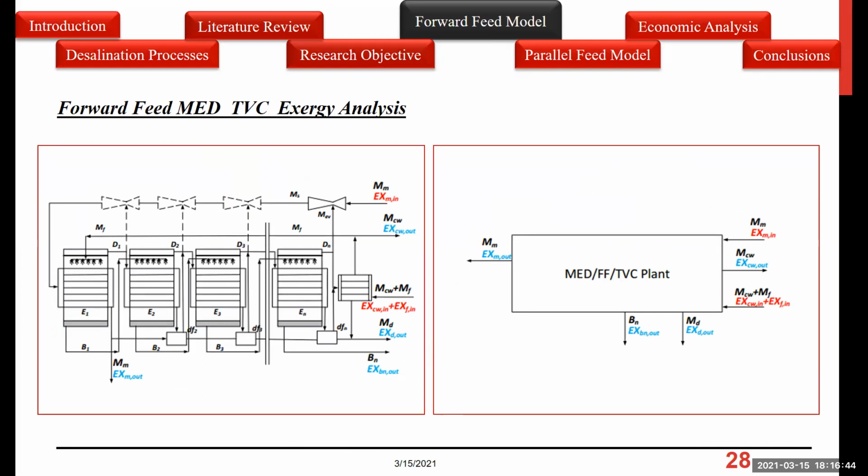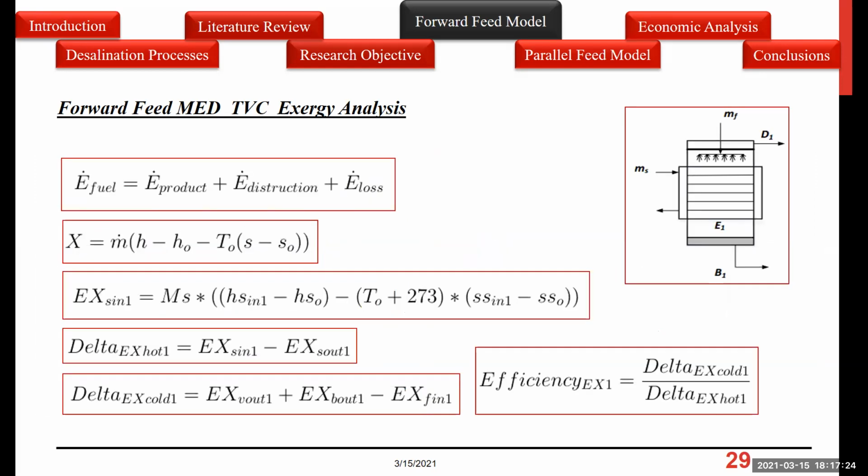Now, this is for the unit analysis. What if we need to do a second law analysis? For the second law analysis, we need to look at what are the entropies in and out. So m dot exit times S exit is equal to m dot inlet times S inlet plus entropy generation plus Q over T. If the system was well insulated, then the Q over T is 0. So we're basically talking about the entropy generation for each one of the components. So after doing the energy analysis for each component, we just write the second law analysis following it.